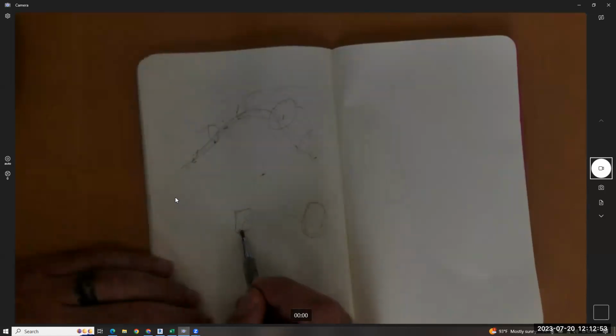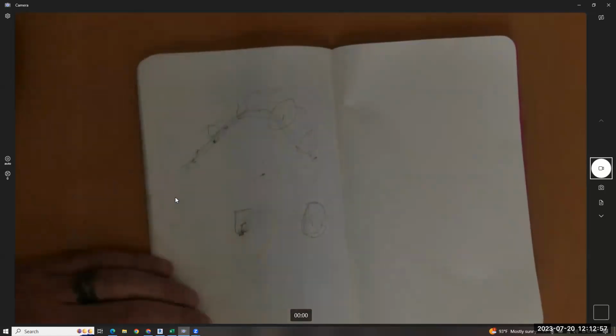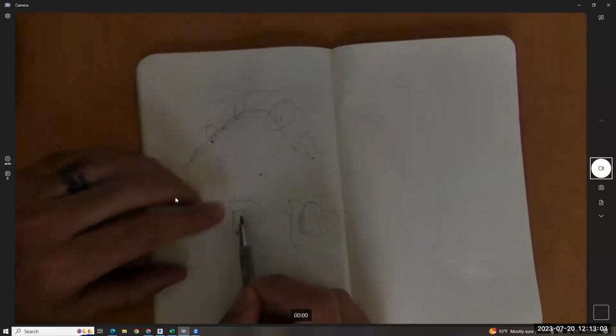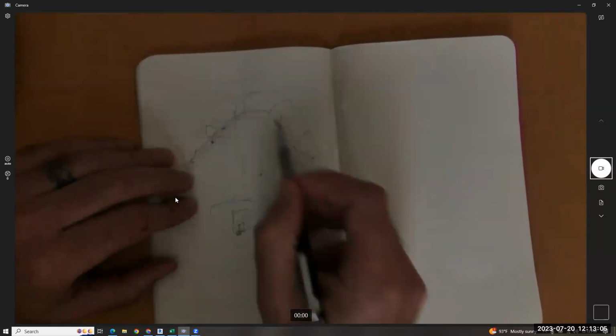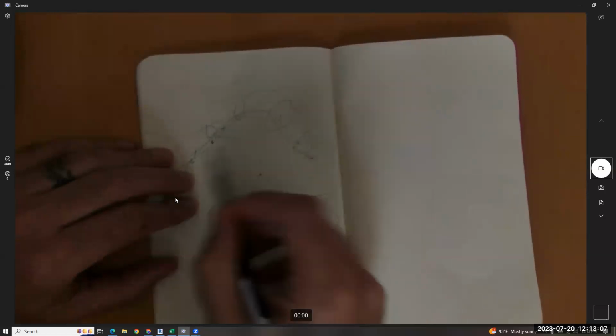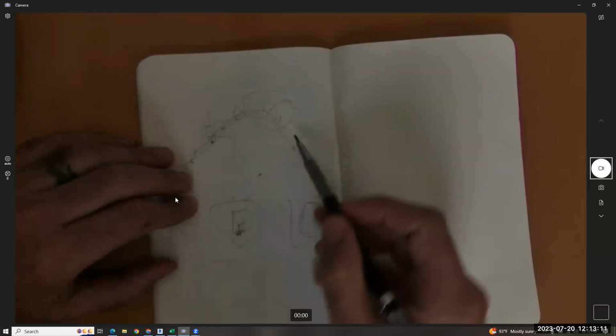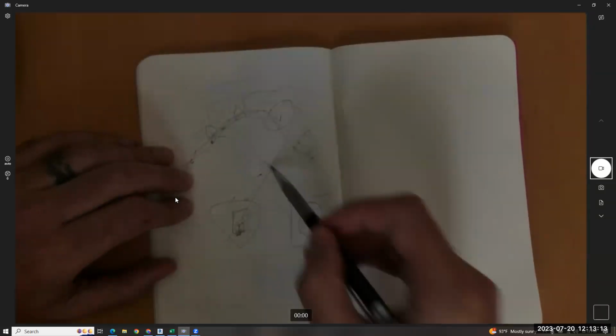So the profile has to rest on a generic model adaptive point to then be loaded onto this independent. No, so this profile is generic model adaptive. Then that generic model adaptive is hosted into another generic model adaptive with a spline. That's how you get a crazy changing cross section. You don't need to do that if you're not changing the cross section.